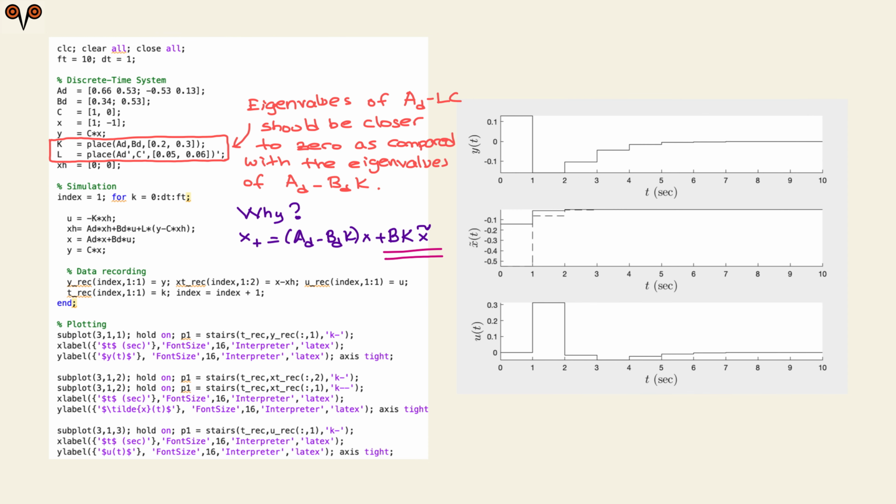All right, you survived. This is the final point that I would like to illustrate in output feedback. Then I will conclude the video. Basically, what is different here? Similar to the previous video, we have AD, BD, C, output, initialization for X, Y. I am choosing K, I am choosing L. Similar to the continuous time case, the observation error needs to die out fast, because if this dies out fast, you approximately recover the state feedback stabilization performance.